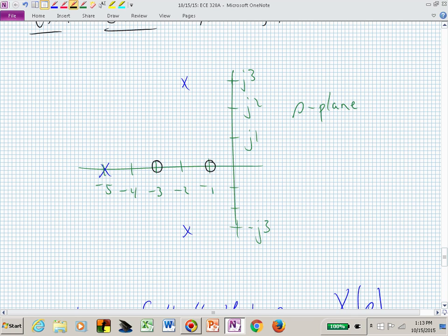If you had x's in the right half plane, what's going to happen? It's going to go up, and we might have a fire truck coming up to rescue you. It might burn up. You might smell it burning. It might go poof. If you're lucky, that's all it does. But if it's in the right half plane, then you have these e to the 6t, e to the t. Those are going unbounded with time. Is that clear? We want to have things in the left half plane, these x's, the poles.